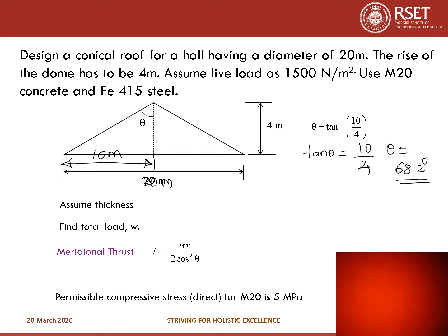Okay, the next step is to assume the thickness of the dome. The minimum thickness you can assume is 75 mm. So here I am assuming 75 mm thickness of the dome. Then calculate the total load.